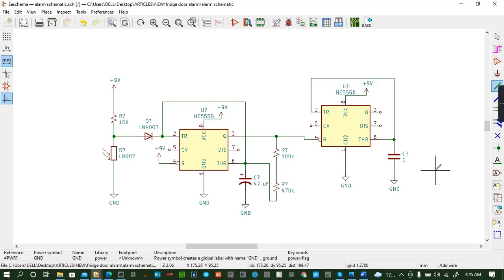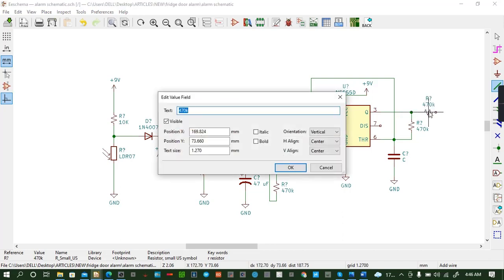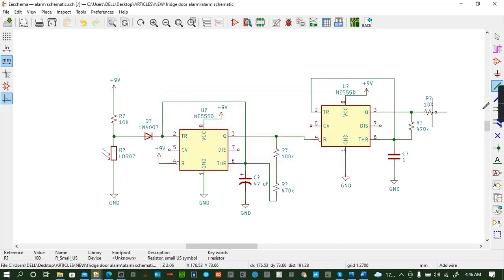So you move to the next bit, which is now the resistor. The 470 resistor is here. We can copy it directly and place it there. Place it somewhere there. This one is interconnected there like that. That's number 3, and then 6 moves from here to that point. We can control save. Then we go to the next bit, which is another resistor, 100. You copy this one. You press R to rotate it like that. You connect it, and then you change the value to 100. Press enter.